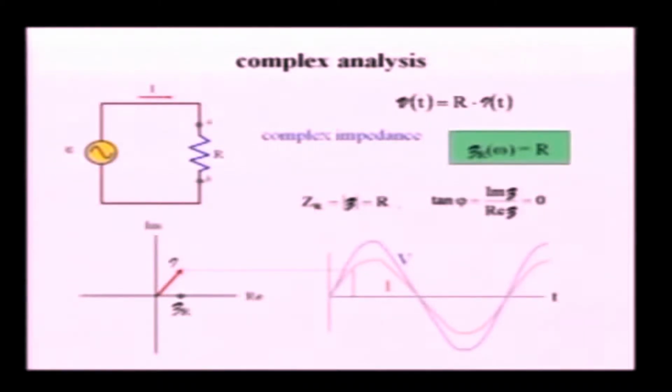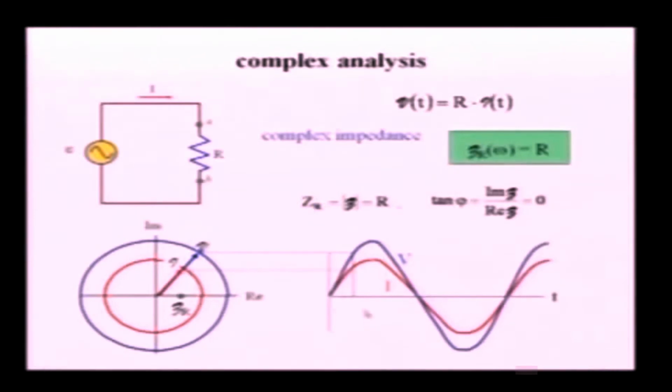Now, how should I draw the phasor representing voltage? Right, it should be parallel. Yeah, the two phasors have to be in the same direction. Over here we actually see that the phases agree. Because where's the phase? Phase is the angle on the phasor diagram. It's the angle between the horizontal axis and the phasor. So both have the same angle. Alright, so as time passes by, both current and voltage oscillate, and the phasors rotate together counterclockwise.